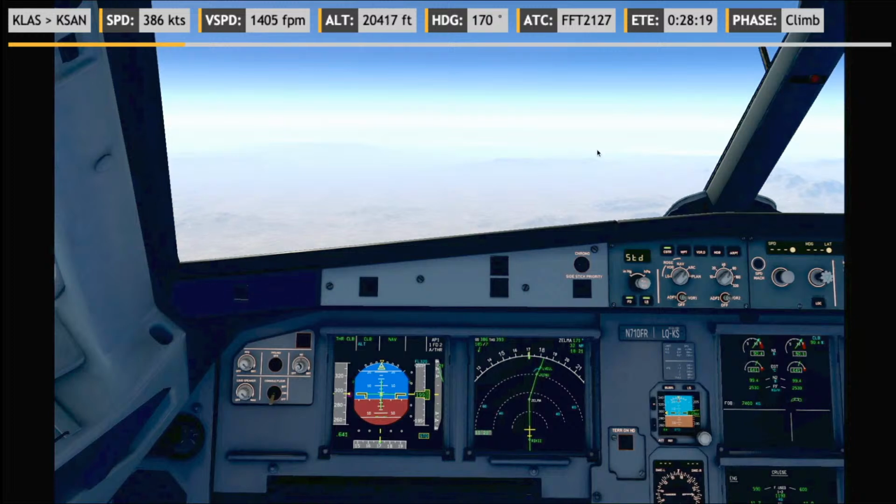I'm gonna do a quick weather update. Let's see what our weather is going to be like in San Diego. Wind 010 at 3 knots. It shifted a bit. It's 40 degrees. No, it's more. It's 100 degrees off, but it's only 3 knots, so we're gonna keep the same approach. It's a lot shorter for us as well. And let's see. 10 statute miles of visibility, no cloud, 24 degrees. Altimeter 30.16, and no remarks that are of interest.